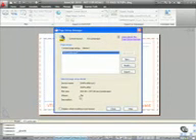Now you'll notice we have A3 landscape in asterisks. That is telling us what the current layout is. We only have the one, which is A3 landscape at the moment, but it doesn't have a page setup. Now it may be that you want to plot this A3 to different sheet sizes. What we're going to concentrate on is having an A3 page setup for our A3 landscape tab. So at the moment, the page setup details just for the tab, for the layout, are a DWF at 420 by 297. That is an A3 sheet.